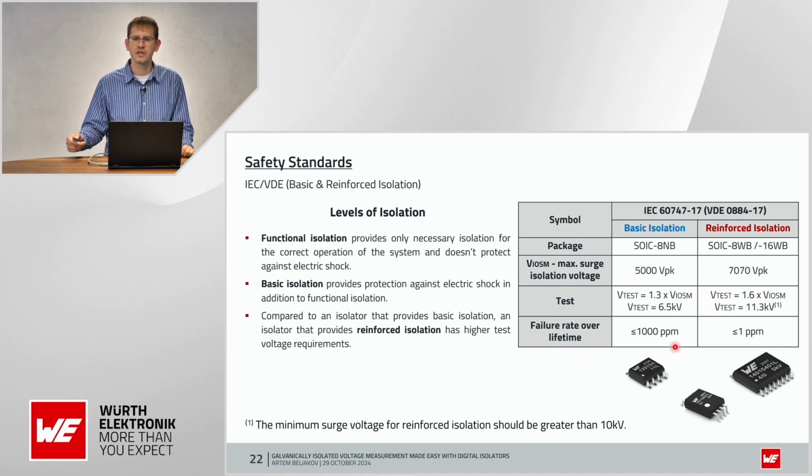And also, it's very important to know and understand that the failure rate over lifetime for products with basic isolation should be less than 1000 ppm, and for reinforced isolation products, it should be less than 1 ppm.